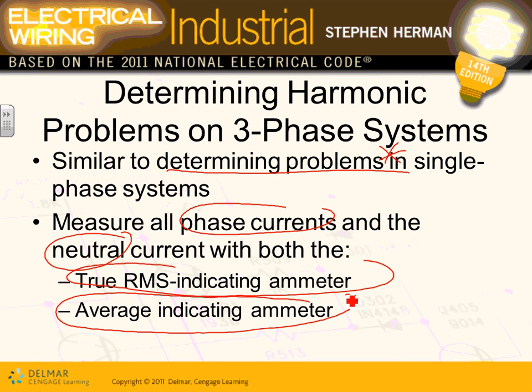We can live with it all the time. If it's the third harmonic and it's too big, then we might have two solutions. Either we oversize equipment or we design a filter. A filter, guys, is a capacitor and a coil and a resistor, an electronic device. They stick it into the system and it sucks that signal. So if it's 120 or 180, it basically locks it and filters it, doesn't allow it to go through. So that's why it's important to know not only that you have a problem, but what type of problem.